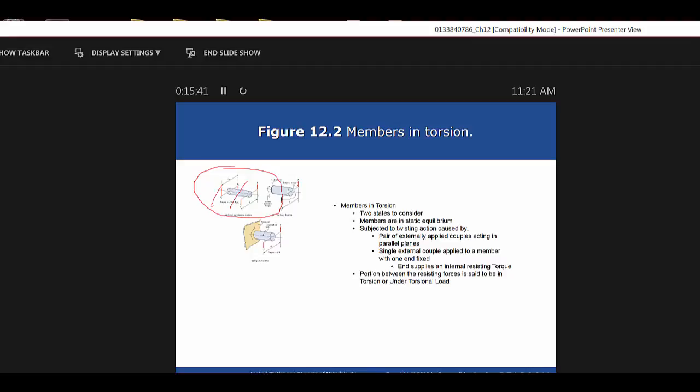So again, that's force times the distance. Note, torque is expressed in units of pounds inches or pounds feet. Okay, you might see pounds feet. They don't talk about pounds feet in here, but on my motorcycle, I'm dealing with pounds feet and pounds inches all the time, depending on what size bolt you're trying to tighten up. The smaller machine screws, you're dealing with pounds inches. When you're dealing with an axle bolt, you're dealing with pounds feet. They make it sound like pounds inches is the only thing you're ever going to deal with. That's not the case.